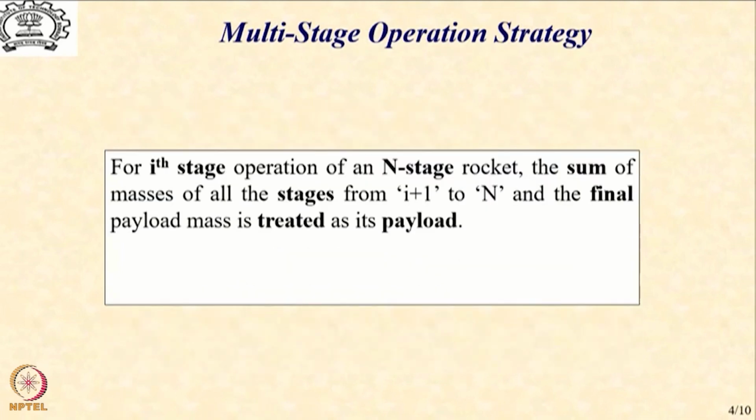So when we say that an ith stage of an n-stage rocket is operating, then for that ith stage, whatever is above it is like a load on it, which means the ith stage is carrying everything starting from the (i+1) stage till the payload end.